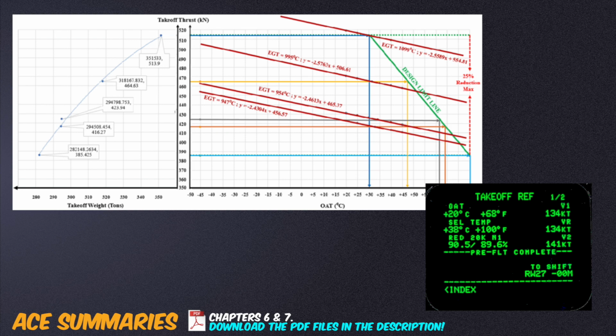That temperature is the highest flex temperature that can be used. Jet engines produce reduced thrust as the ambient air temperature increases. The flex temperature is the highest air temperature at which the engines would produce the required thrust. The crew finds that temperature and enters it into the FMS, effectively telling the computer to assume that the specified air temperature, instead of the actual air temperature, is present.